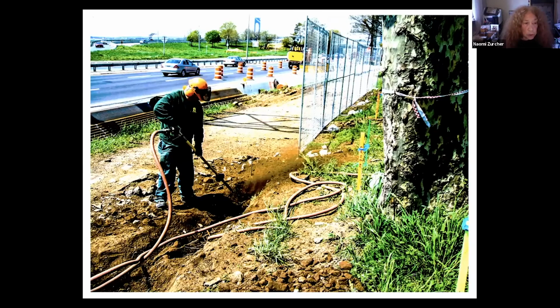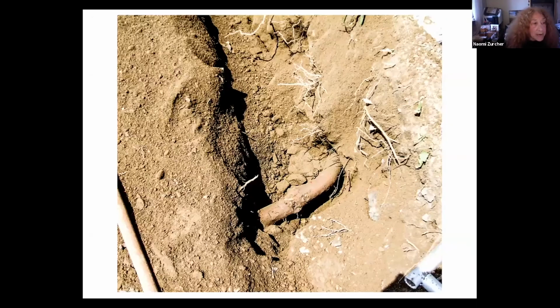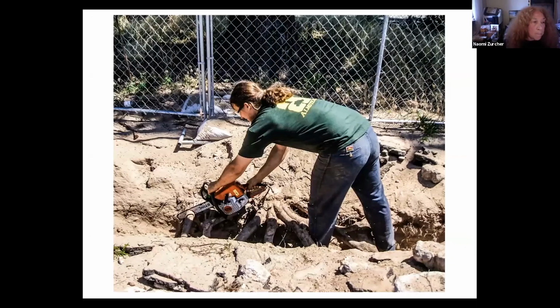The structural roots of all protected trees that extend into the work footprint should be accessed using pneumatic excavation, such as an air spade, along with an air vac to collect the removed soil. Enabling accurate root pruning perpendicular to the root's growth at the point of the cut of one root zone quadrant, the wrapping of exposed roots using moist burlap, and the replacement of removed soil immediately following pruning.